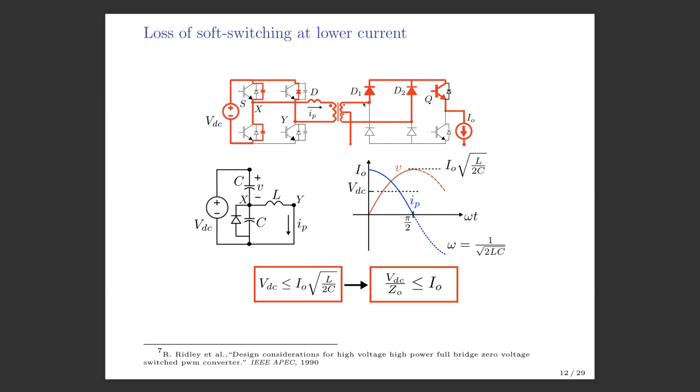And if it forward biases diode D2, then D1 and D2 will basically short this transformer winding, right? And so that means effectively this part will become electrically shorted. So that is what I'm showing here. This is an equivalent circuit of this particular state of this circuit, right?